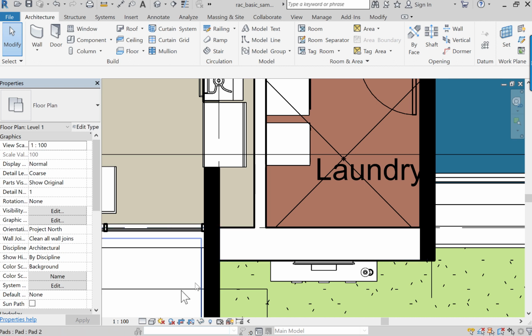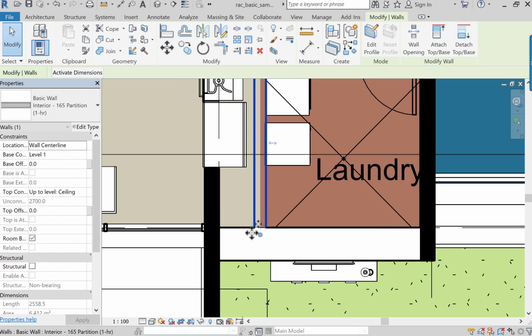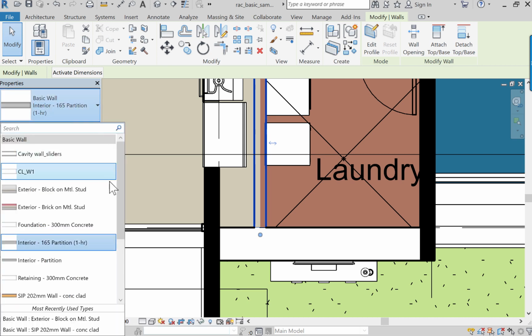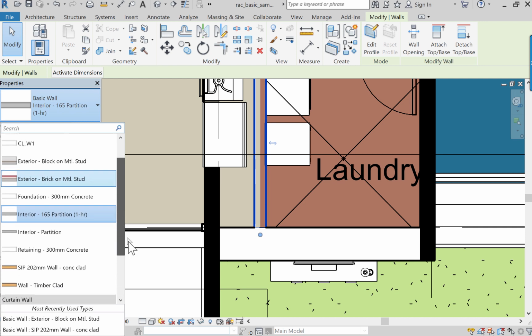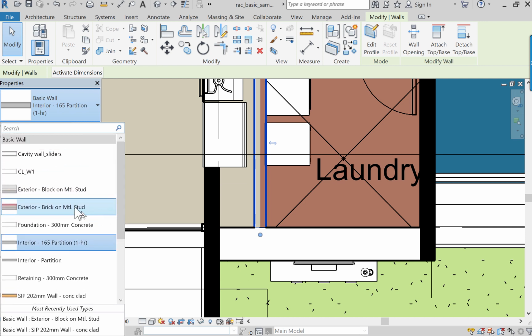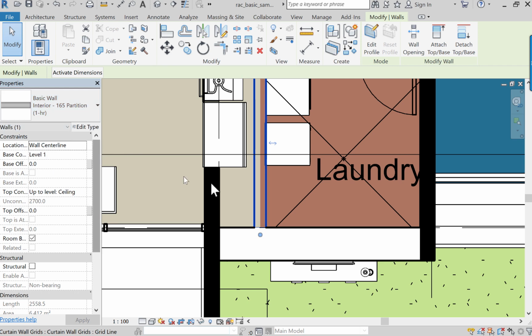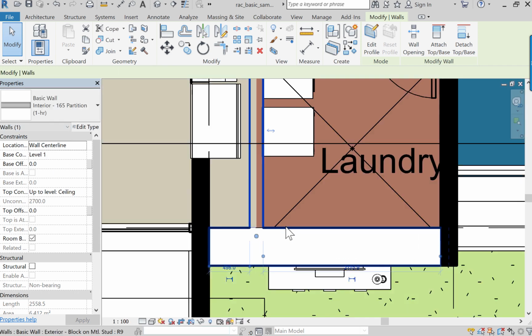I don't see all the internal workings of this wall. And when I choose walls, I tend to have only a few wall types instead of using some of these which are 1 hour rated, and so on. They have all the elements of the wall in them. I usually just use a generic one. It's a lot easier than using the complicated ones.